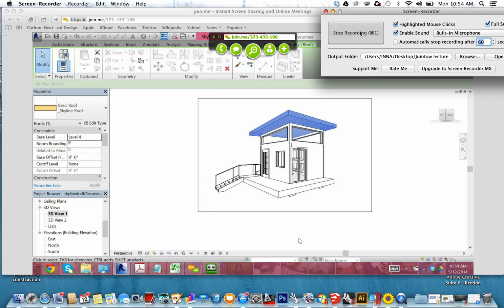Okay, which way do we? Well, actually, you know what? The problem is if the joists are running this way. I think it works actually because of the 45-degree angle. Yeah, because you need to run the decking so that the structure hits it. You don't want to run it parallel to the structure, but our structure is at a 45-degree angle to this, and so it might be okay. Okay, so that's that. All right.